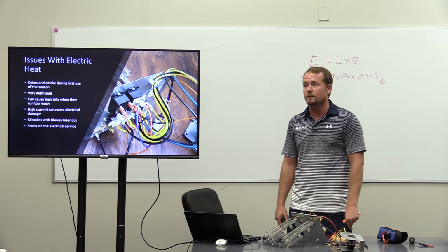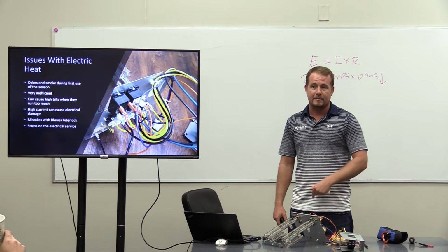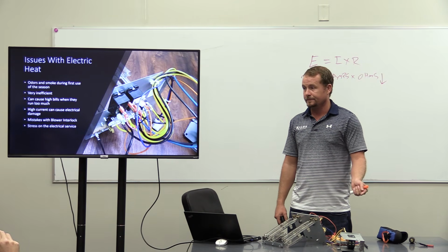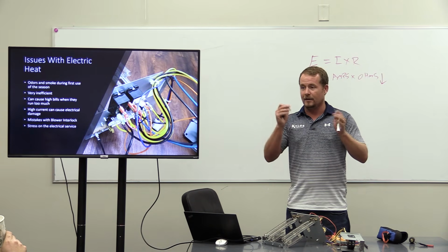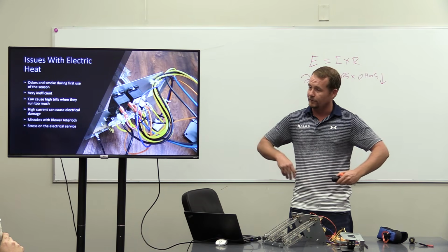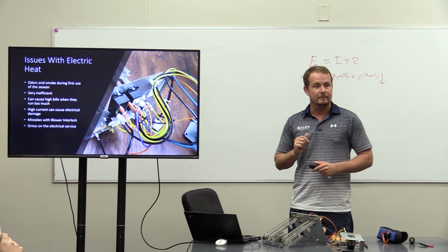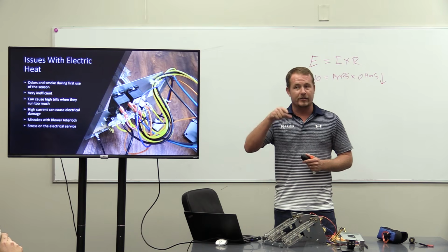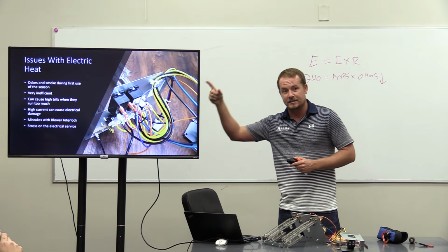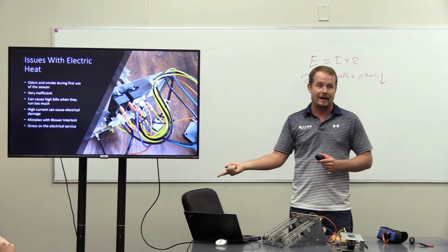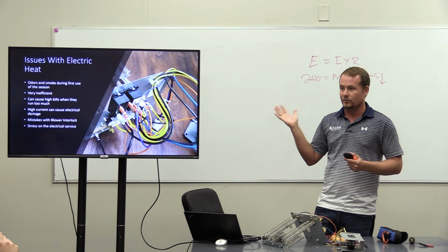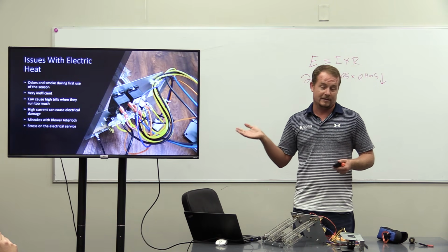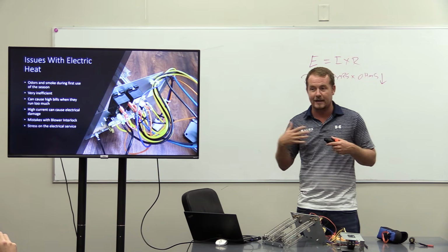You got a lot of older homes that are running gas that may have a 100 amp service on the house. So you may be able to slam an electrical panel in there. Well, hey, I can put a new panel in, run some new wires, put a breaker in, good to go, right? But did you think about the breaker that runs the entire house and the wires that feed the entire house? How often do we think about that with what we do? Like never, right? Because that's not my job, right? Not my job to worry about that.